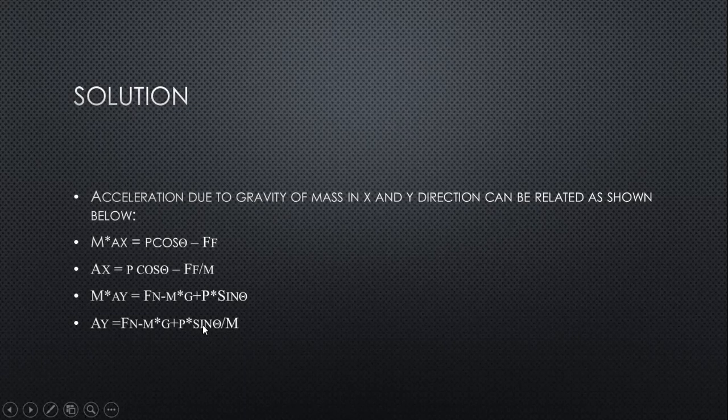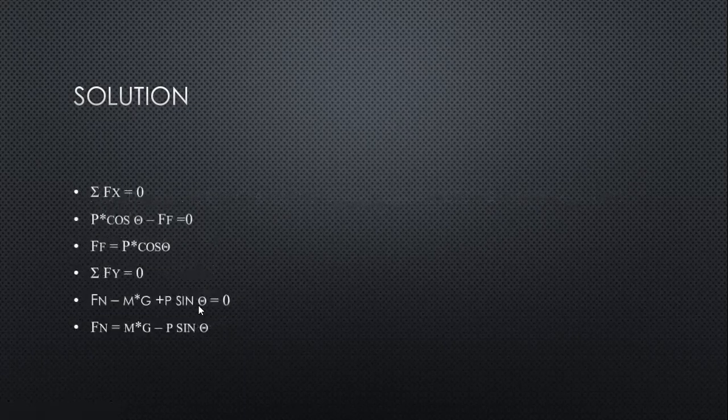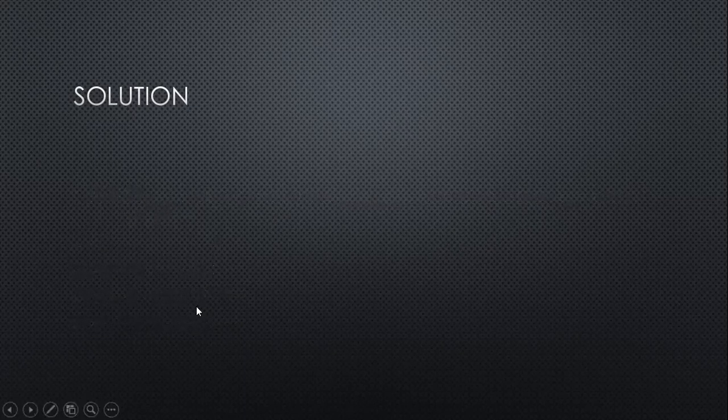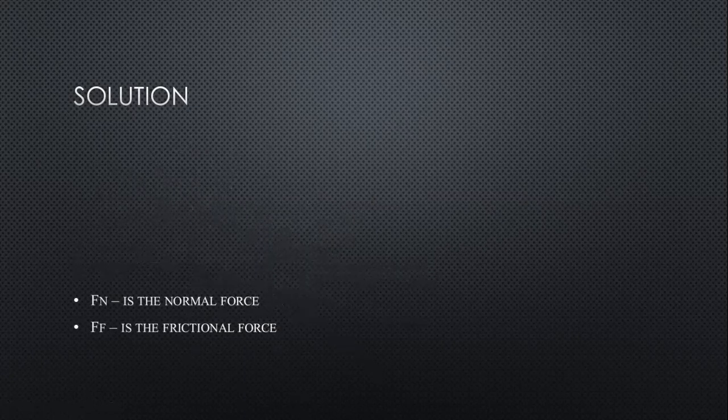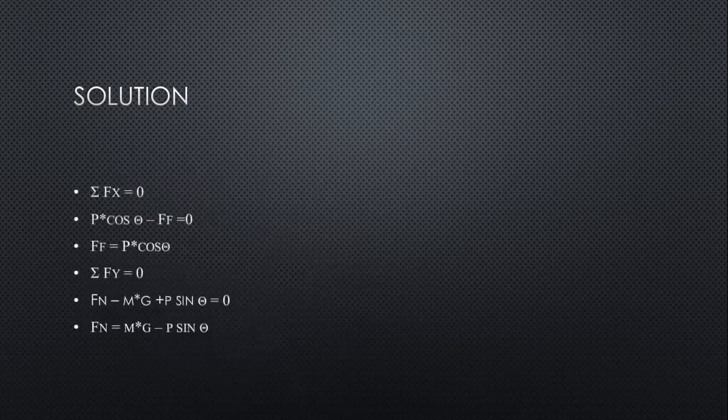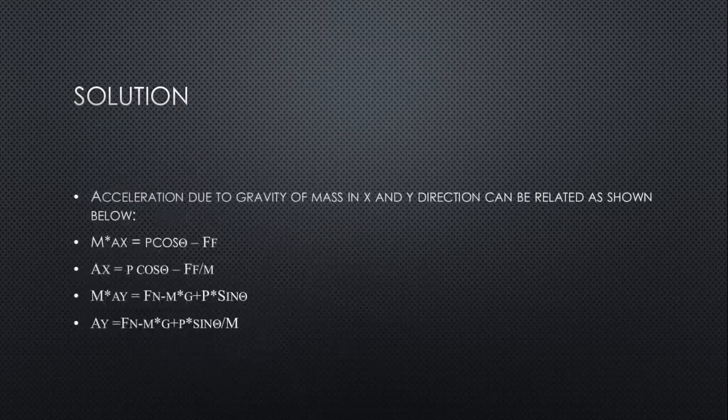So in this problem, we have drawn the free body diagram of the rigid block, and we discussed how to resolve the forces horizontally and vertically, find the frictional force and normal force by resolving the force components, then estimate the acceleration based on the weight placed on the rigid body in the x and y directions.